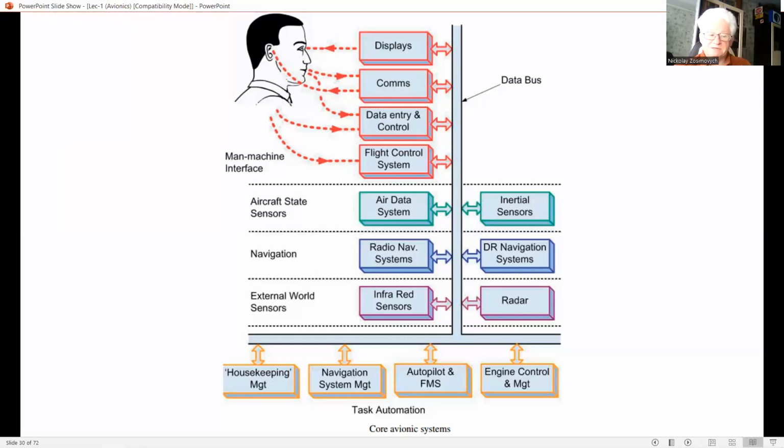The flight control system exploits electronic system technology in two areas, namely auto-stabilization or stability augmentation systems, and FBW flight control systems. Most swept wing jet aircraft exhibit a lightly damped short period oscillatory motion about the yaw and roll axis at certain height and speed conditions, known as Dutch roll, and require at least a yaw auto-stabilizer system to damp and suppress these modes.